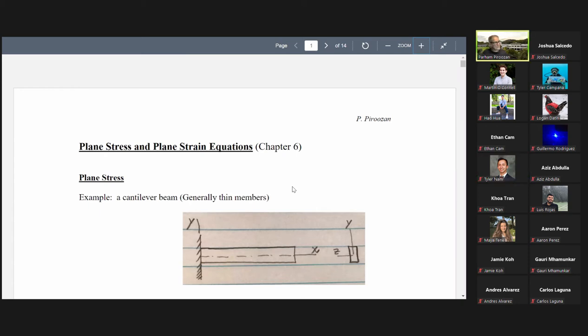You're right. Continuum elements are two-dimensional or three-dimensional elements. Unlike the structural elements, which were line elements, we use them for trusses, for beams, for frames, for bars. But these are two-dimensional or three-dimensional elements called continuum elements. So the two-dimensional elements that we use are triangular elements with 3 nodes, triangular elements with 6 nodes, and so on and so forth. So today we are going to discuss continuum elements, two-dimensional. But first, an introduction to plane stress and plane strain.